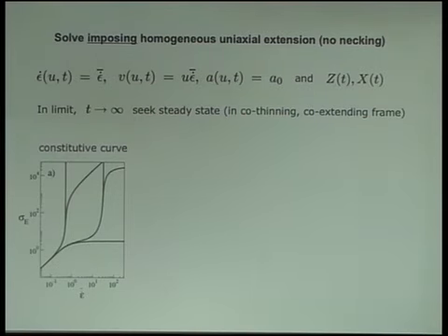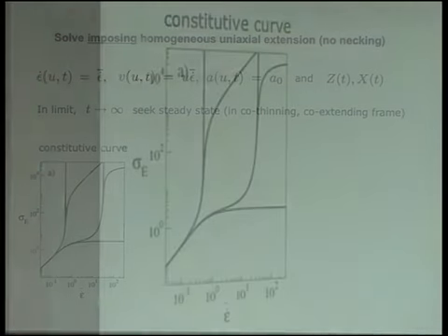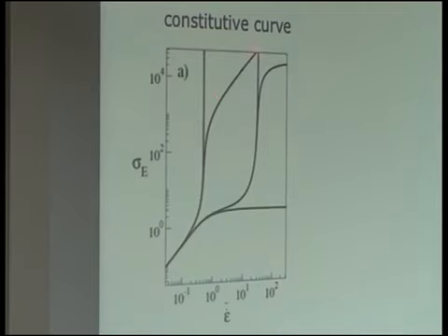And that's because the Oldroyd-B model is based on thinking about extensible dumbbells in flow, and there's nothing to stop them from extending infinitely, and that's what happens beyond a critical flow rate. That is mitigated by putting in nonlinear relaxation terms in the case of the Giesekus model. That's what this one is here. The FENE-P model, for a value of a parameter that's chosen to correspond to something that looks similar in the Giesekus model, actually that constitutive curve overlies. So that's both Giesekus and FENE-P.